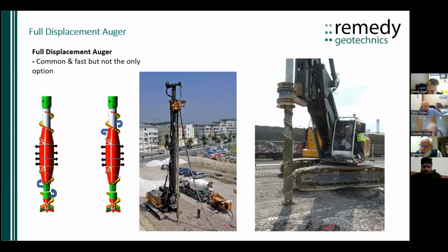So yes, obviously, relative stiffness of ground and inclusion is important and does affect the loads that are shared between the ground and the column. Although I would say in practice, because you're probably going to be using the columns through fairly soft ground, the difference in stiffness is going to be great.